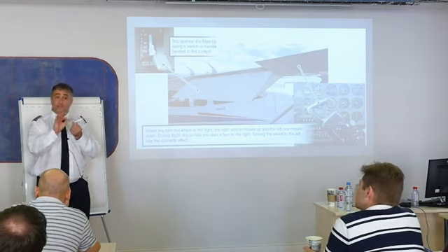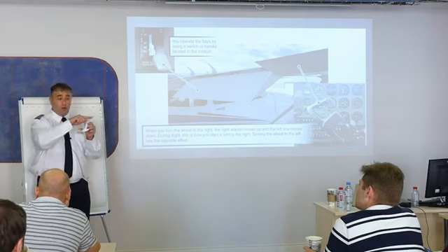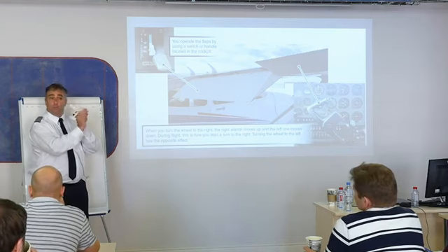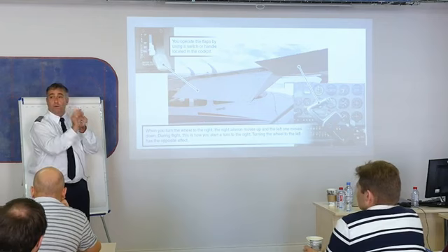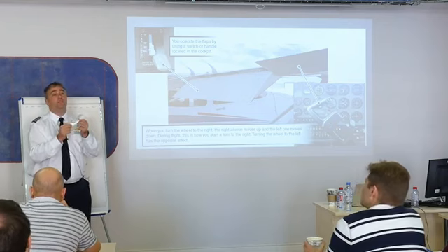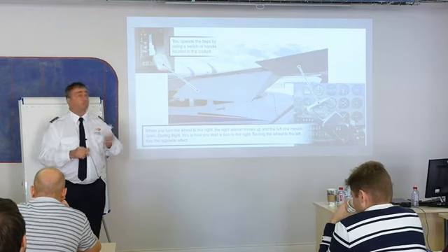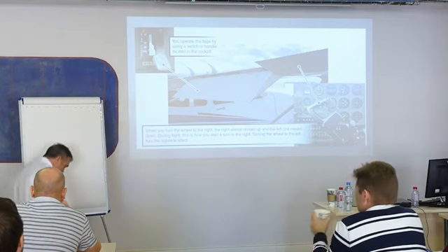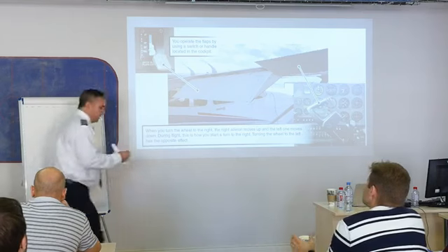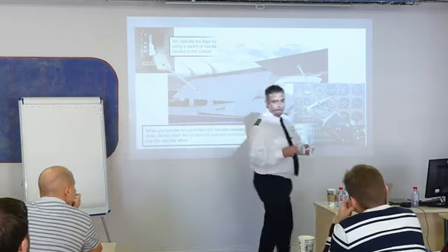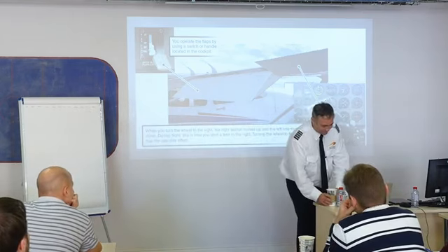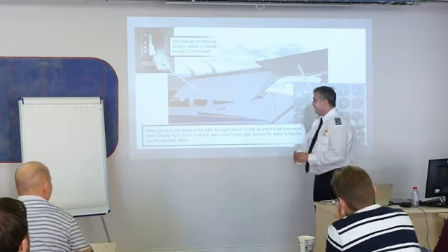Number one, it gives you the most amount of arm, right? Or the most amount of power while you're trying to bank the airplane. It also gives you the maximum controllability while you're close to a stall. So that's why the ailerons are on the outside. Okay. It's not uncommon to have some part of the airplane fall apart when I'm flying it. All right, or at least in a scenario.